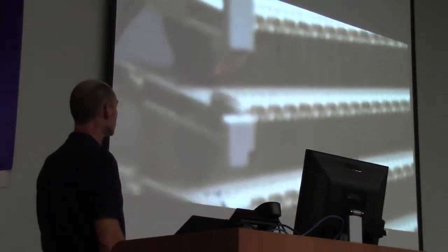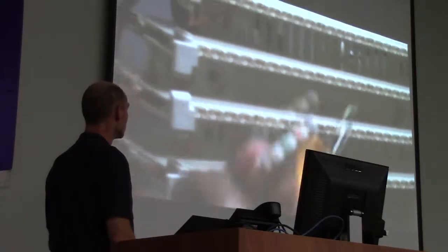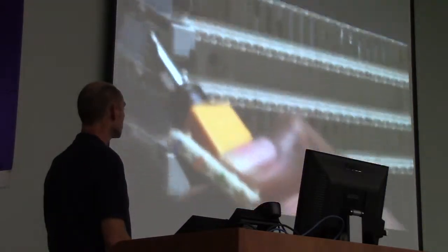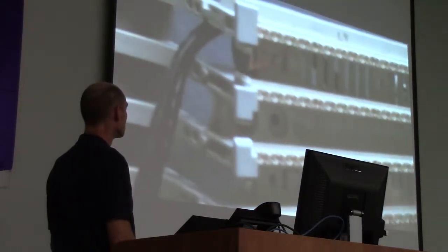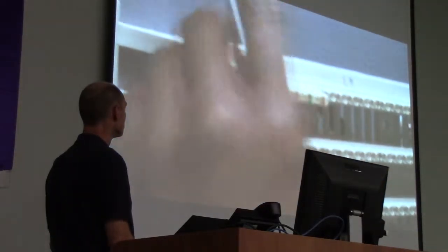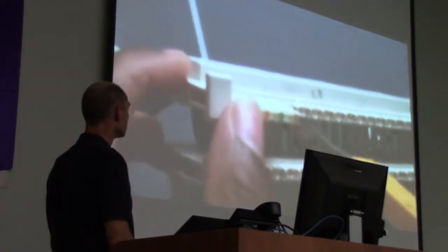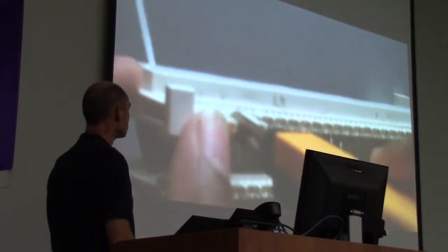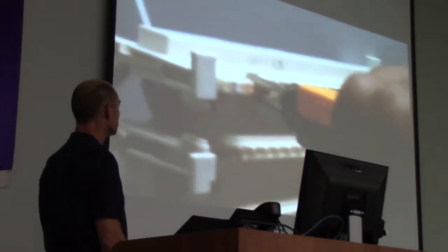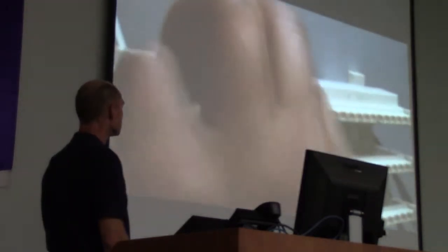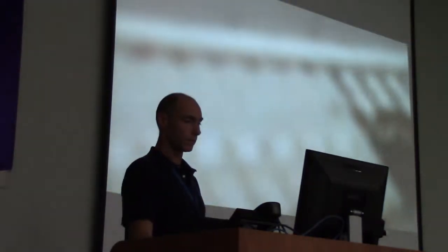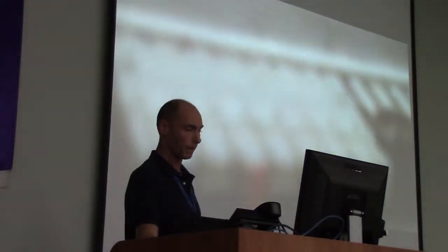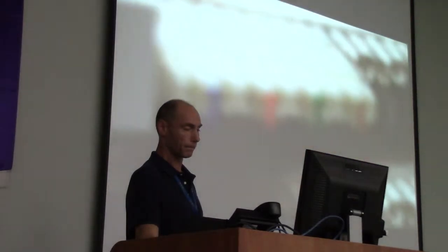Then you grab your C4 clip. This is a C4 clip, which is color coded the same way I just punched it down here. So I put it on first. Normally I just put mine right there on the white green and give it a good hit. See at the top, there's little notches that catch it that make sure it's secure. And I will continue to do that all the way through.